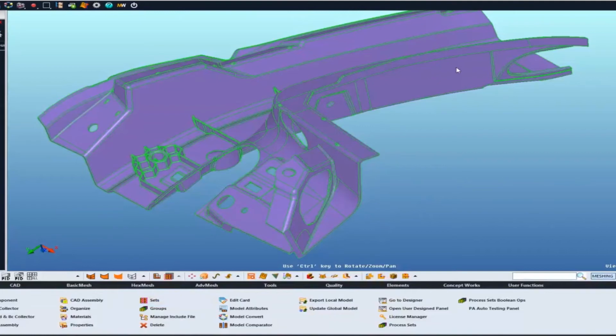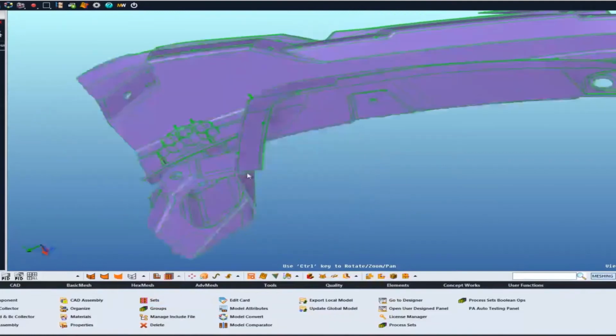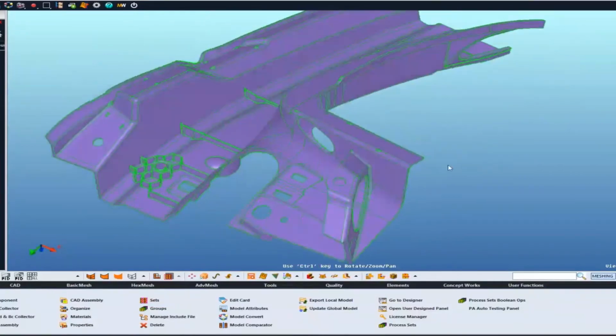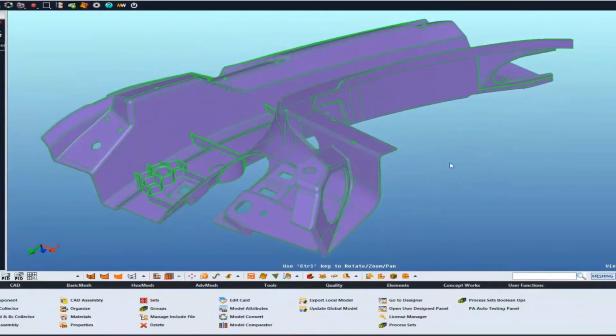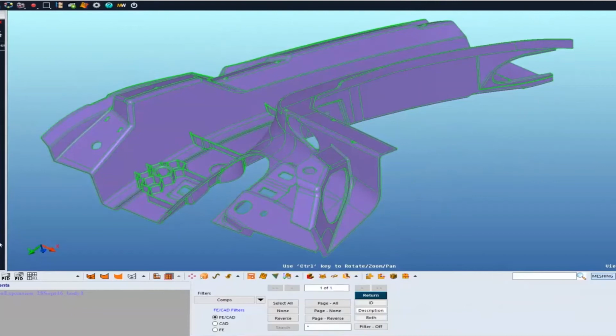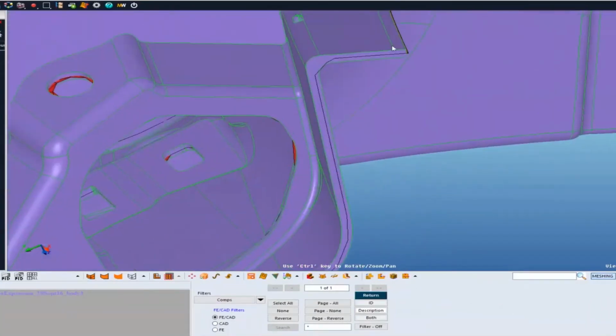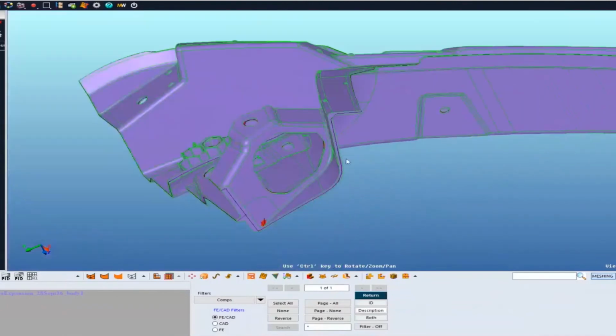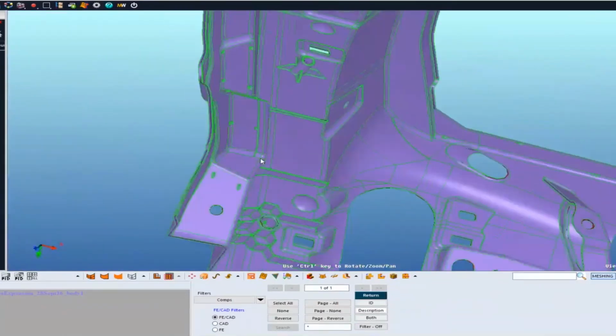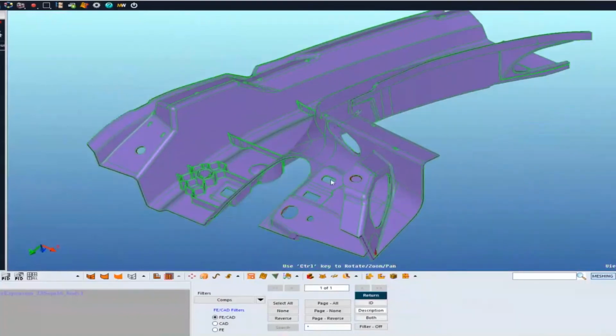So here we see a plastic injection model on the screen. Now we have a few models. I will quickly go ahead and show the nominal mesh. This is our nominal CAD, which is a 3D part. We also have a nominal mesh, which is exactly sitting at the midplane of this CAD, as we can see on the screen.